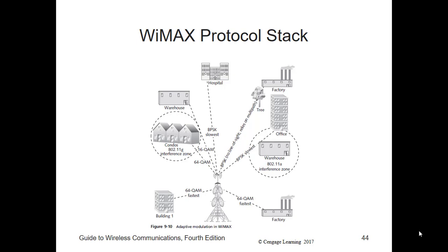Now, the BS sends information to the SSs about which modulations it will use for a particular burst, which is our signal being sent, and for a particular SS in the first few data frames at the beginning of the transmission. The SSs then will respond by sending information to the BS at the beginning of their assigned bursts.